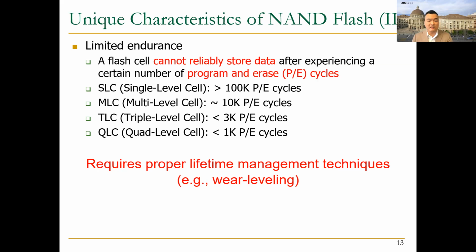So it is really important to keep the P/E cycle variation across the blocks as low as possible to maximally use the potential endurance of underlying NAND flash chips.